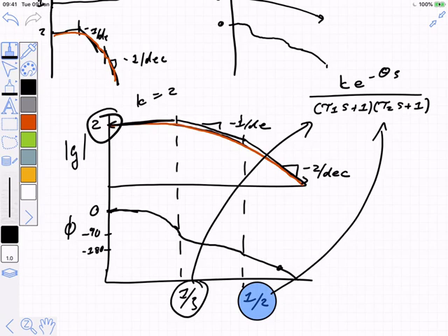And the only reliable way of actually knowing the dead time is to take all of that known knowledge that I have already and then calculate the dead time based on a measurement that I've made in the higher frequency area. I can see, okay, at this particular frequency, the phase is exactly this, and I can then back calculate for the dead time.